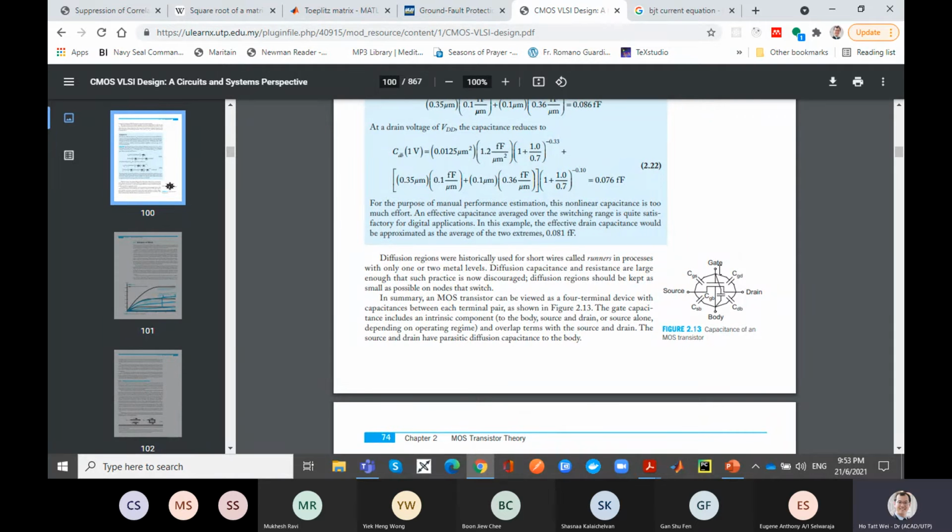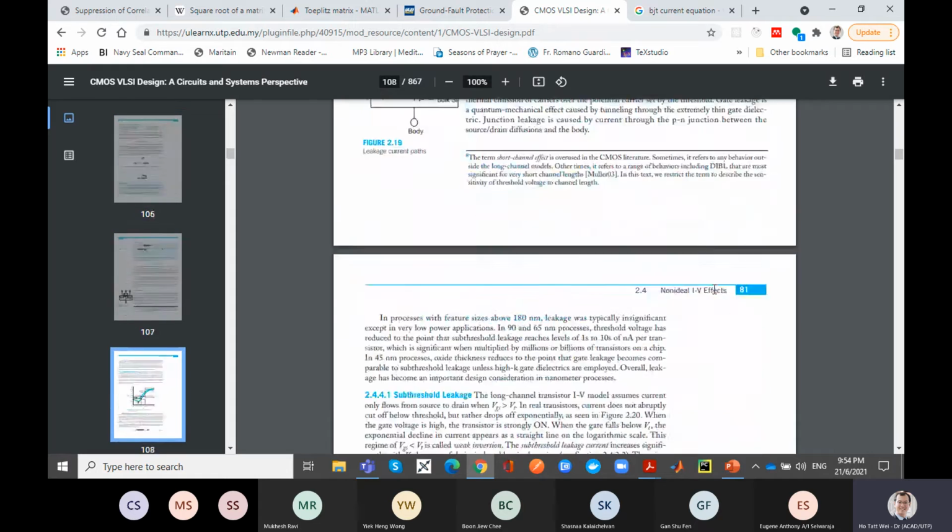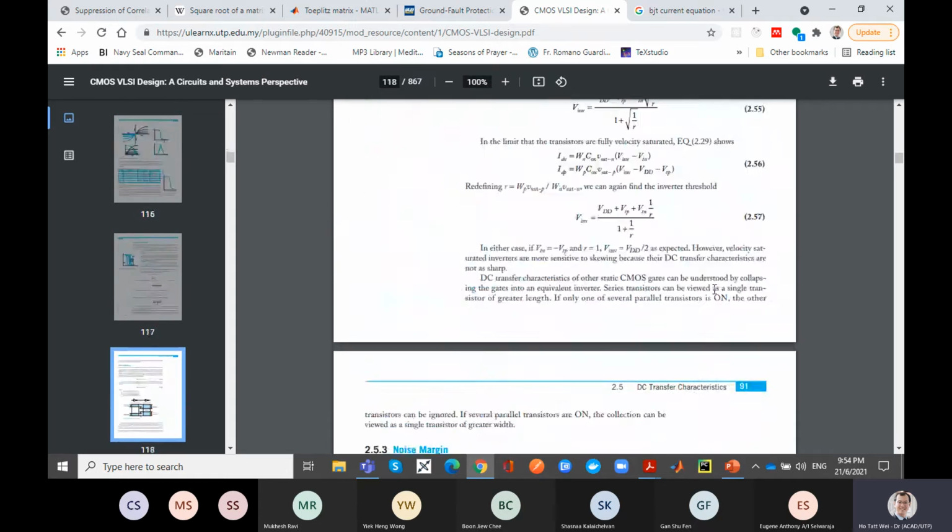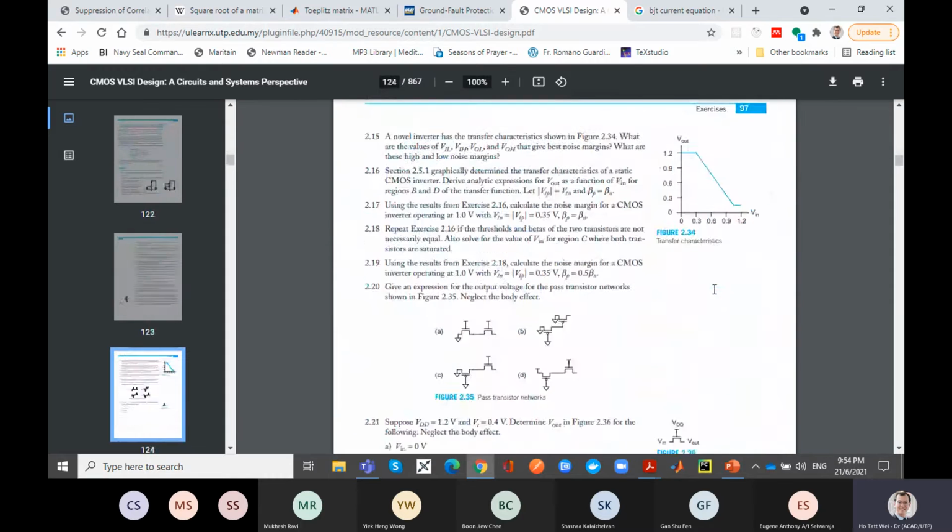If your voltage VGS is fixed, then this is called a strong pull-up. That means your MOSFET is on. But there is a case where, as the circuit operates, the source voltage is going to change, so your VGS is changing and reducing.